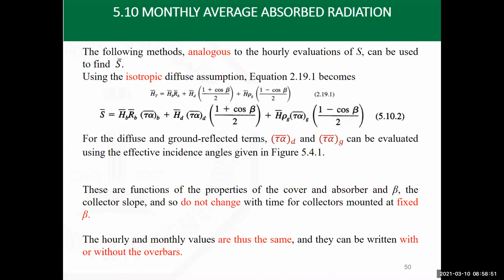So you would know that you are cutting 50% or 40% or whatever from the electric consumption, and you are relying on solar or renewable energy. Someone else would say, no, I want to make it 100%. That means you will need more collectors. This kind of analysis is within the F-chart method, and there is even software that does that.